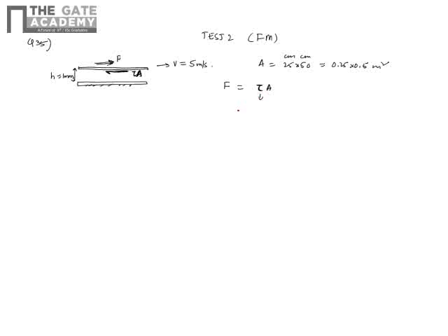Now for the shear stress due to viscosity, we have to use Newton's law of viscosity, which says that the shear stress developed depends on, assuming that the flow that has been set up is linear in nature. Since the gap is small, the flow can be assumed as linear. So the shear stress that is offered by the fluid depends on the velocity gradient. It is defined as viscosity into velocity gradient, and for a linear velocity profile, we can write V by H. So this can be written as mu V by H into A.